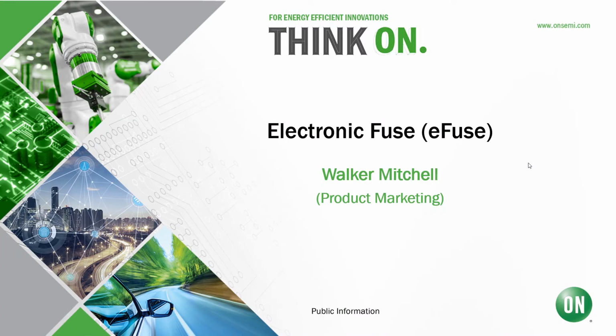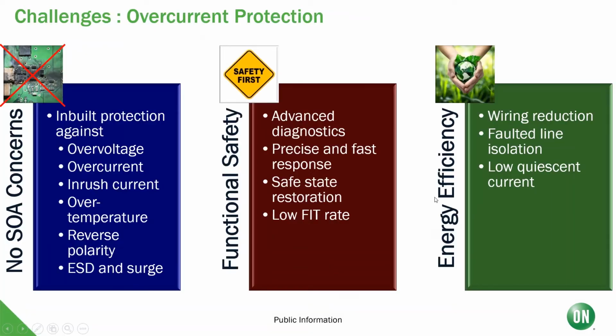In this video, we will quickly discuss what an eFuse is, what the key applications are, and our current product offering. There are a few key challenges when trying to implement overcurrent protection in modern systems. The first challenge is guaranteeing the SOA, or safe operating area, of the end application. In order to guarantee the SOA, you need to protect against overvoltage, overcurrent, inrush current, overtemperature, ESD surge protection, and in many cases, reverse polarity protection.